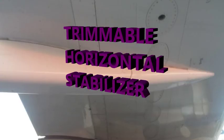We also have your THS, which is your Trimmable Horizontal Stabilizer. It's a fully moving horizontal tail surface. That also reduces the drag, as the stabilizer surface and the elevator are in alignment whenever the aircraft is in trim mode. That trim is for reducing the drag.